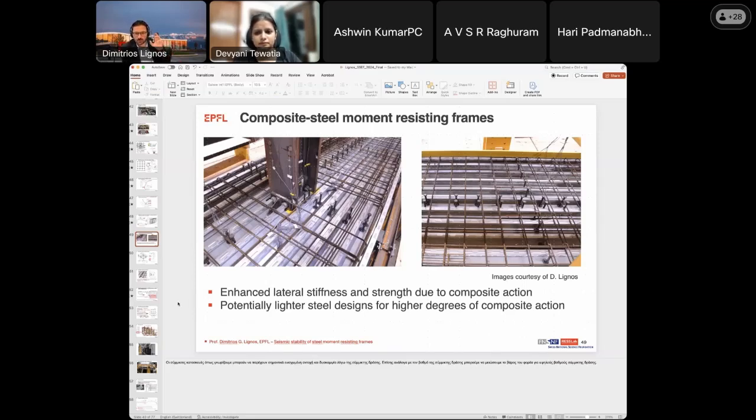So in short, I would not weld within that zone, but this is not so important when it comes to leveraging the composite action, because what really matters is what happens around the column and how the column face bears on the slab. If you would like to leverage the composite action, you don't need the studs within 1.5 times the depth, and you have to ensure that you don't prevent bearing of the column flange against the slab.